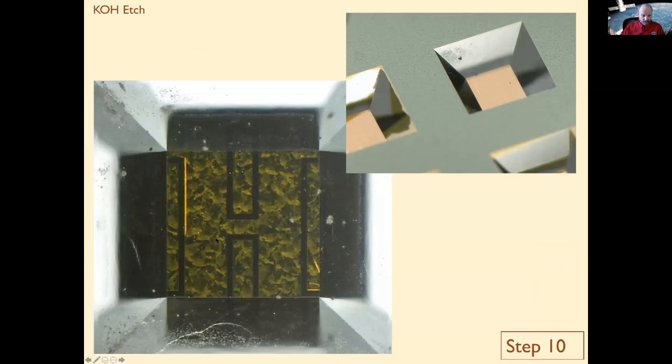And then if you zoom in on it, look at it top down, you can actually see the membrane, right? It's a polycrystalline structure, okay? And then you actually see the Wheatstone bridge resistors on top of the membrane. Remember, we're looking from the back of the wafer to the membrane.